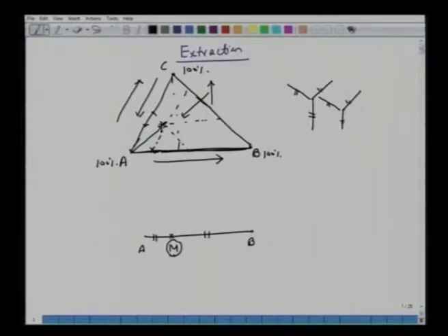So again, you apply the mixing rule here. A by B will be equal to xm minus xb, so the other side of this segment, over xa minus xm, or minus xm plus xa to make it positive. So no C here, which means if we add a certain amount of pure C and I draw a line like this, then I have the mixture, so I call it M here. So I have M and M prime here.